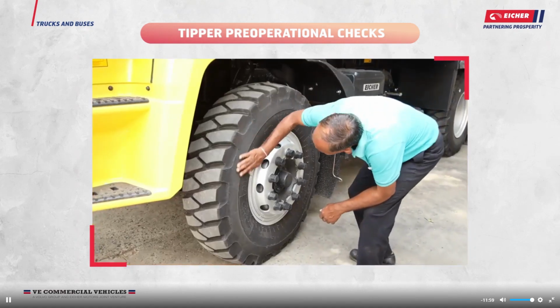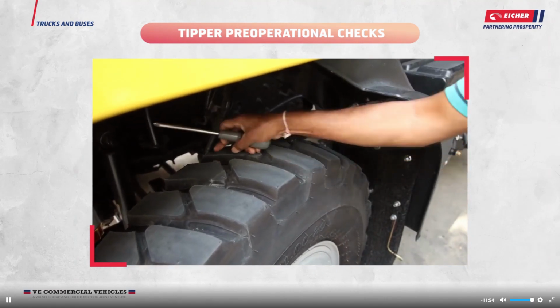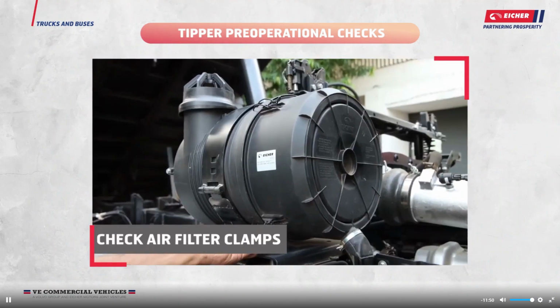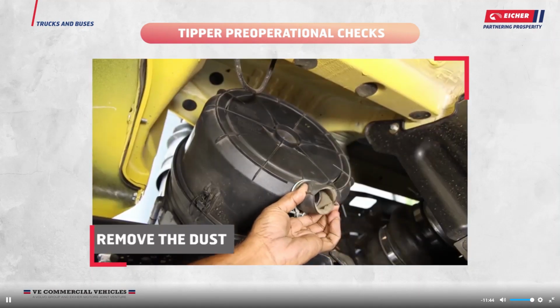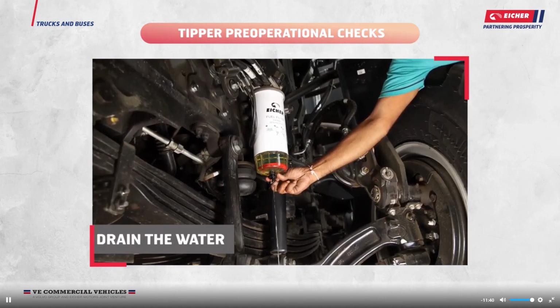Check tires for damages, wear and tear, and any foreign objects or rocks stuck in the tire treads and between dual tires. Check air filter clamps are properly clamped. Remove the dust from air filter evacuator valve. Check and drain the water from water separator.